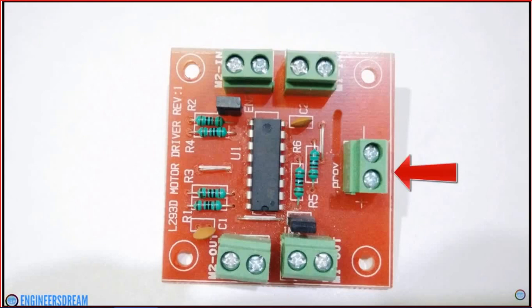You can also see that there is 1 more green socket on the right side, and to this green socket, I had to give external power using a battery. The advantage that I found of using this motor driver is that I did not have to give 5 volts of supply separately to this motor driver breakout from my Arduino, because the circuitry of this breakout board is made in such a way that the VCC and the enable pins get the required 5 volts from the external battery itself. So in short, the motor driver basically converts the incoming supply from the battery and gives 5 volts of power to the pins that require 5 volts.